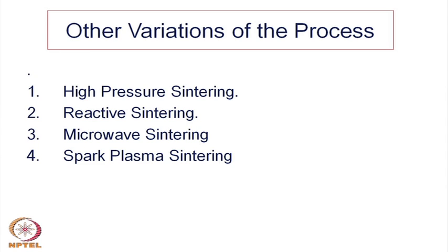In addition, we have microwave sintering. The only difference here, of course, is the mechanism of heating. The way the compact is heated to high temperature is completely different. This we will discuss later on, what is the advantage or disadvantage of microwave sintering. Every material cannot be heated by microwave. There are certain dielectric characteristics required for microwave sintering. But if those characteristics are met, microwave sintering is a very good heating process. By that heating process one can also get sintering, because heating is one of the prerequisites of sintering.